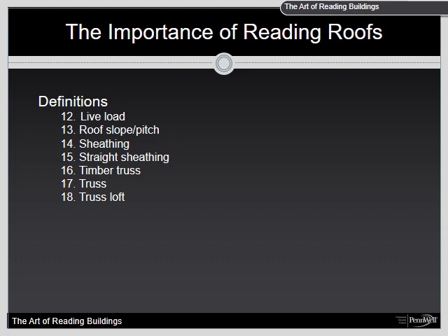Sheeting. All manner of material used to cover or encase walls, ceilings, and roofs of frame structures. For a roof, it is the first layer of covering for joists, trusses, structural beams, or rafters, and is found in solid or open sheeting arrangements. Solid sheeting arrangements include OSB, plywood, or other panels, as well as solid boards that are butted tightly together.